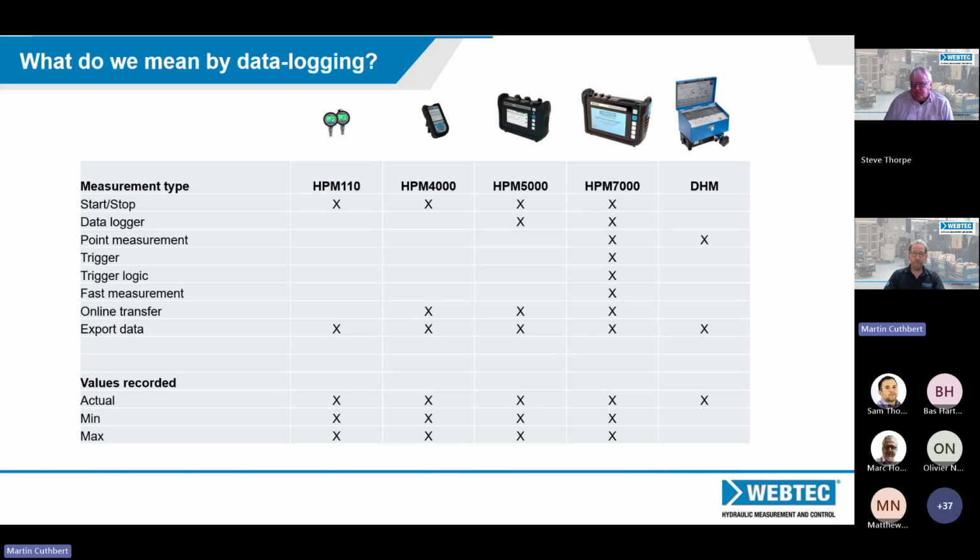So maybe the pump's at full flow and at no load. As you progressively load it with the load valve, the pressure goes up and the flow comes down. And for each of those test points, you might just log a point on the tester and save that to memory. And then you end up with 10 or 20 points of data, which are then very handy to produce a certificate. And again, we'll touch on that a bit later on.